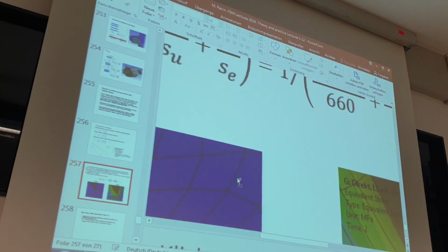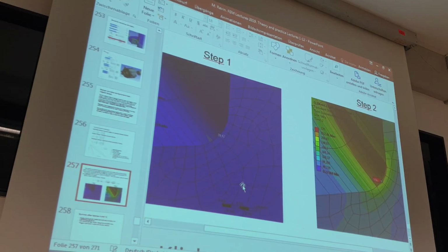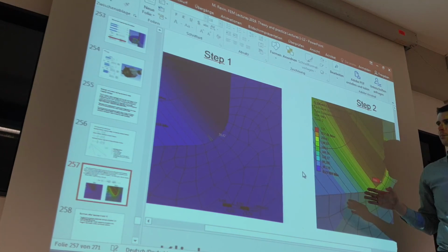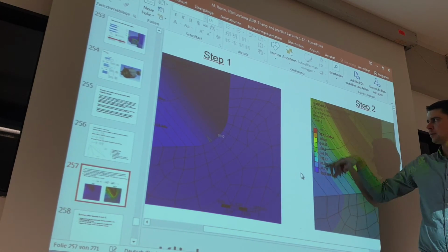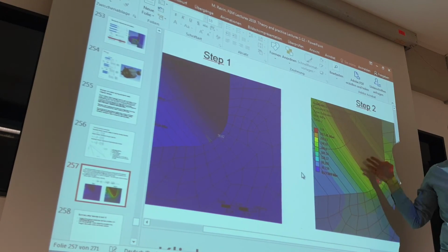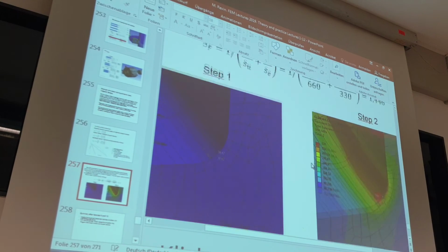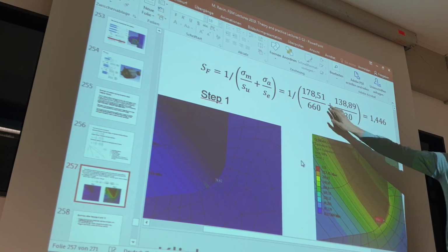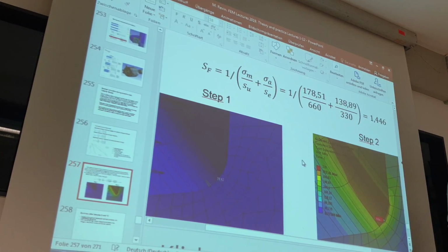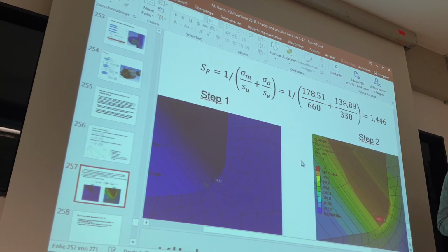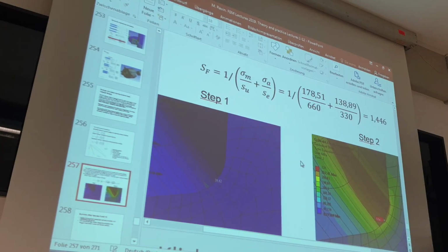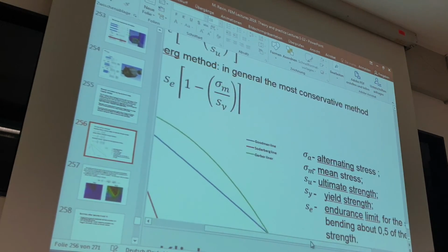It's okay, looks about 39, and here 307. So what it means: my middle stress is the sum divided by 2, it's my middle, and my amplitude is maximum minus middle stress. If I do it, I have middle stress 180, amplitude 183. And if I use now this safety factor, I have 1.4 safety. And these points I can write here.